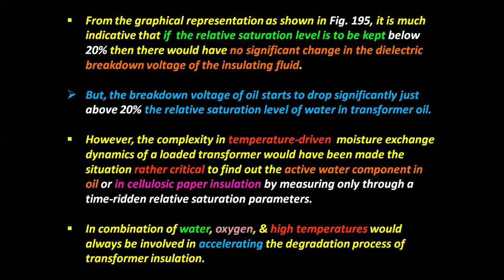From the graphical representation shown in figure 195, it is quite indicative that if the relative saturation level is kept below 20%, then there would be no significant change in the dielectric breakdown voltage of the insulating fluid. But the breakdown voltage of oil starts to drop significantly just above 20% relative saturation level of water in transformer oil.